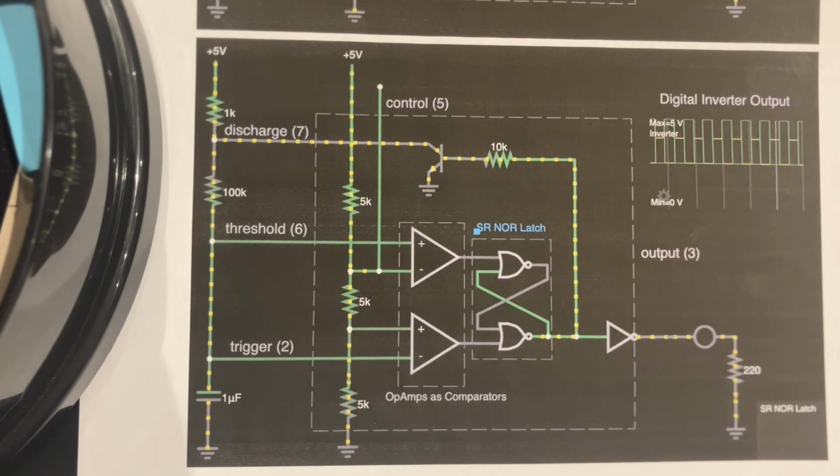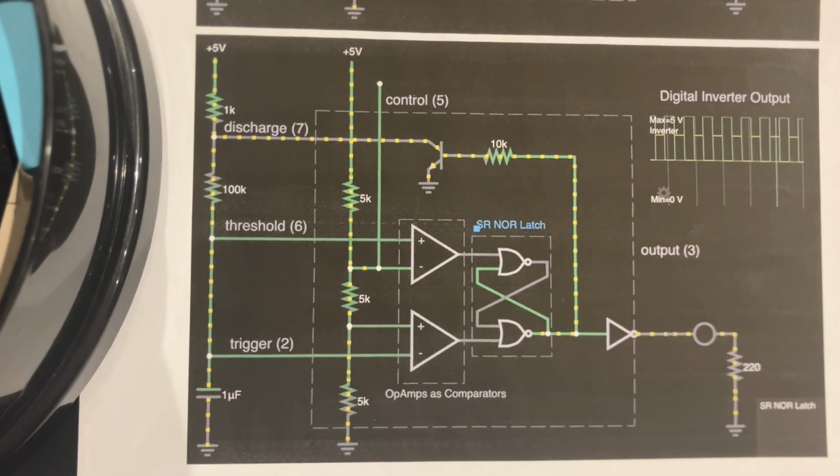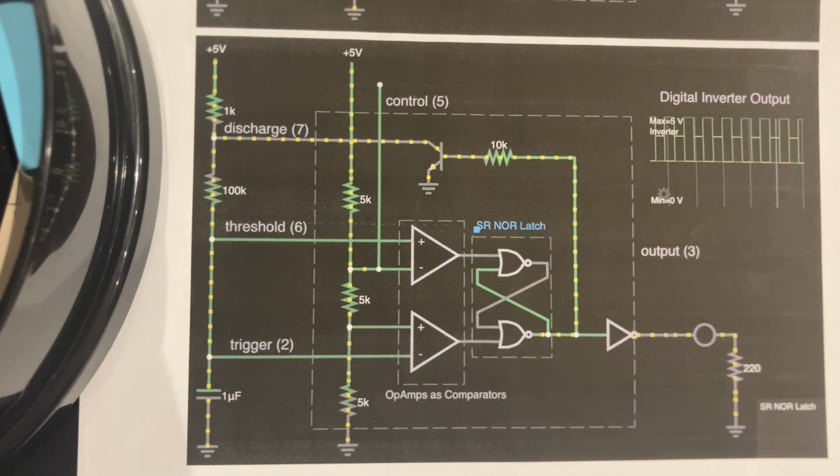The capacitor begins charging again and the LED output goes high. The astable 555 will continuously oscillate between these two states. This creates a continuous digital square wave output, which is displayed using an LED.